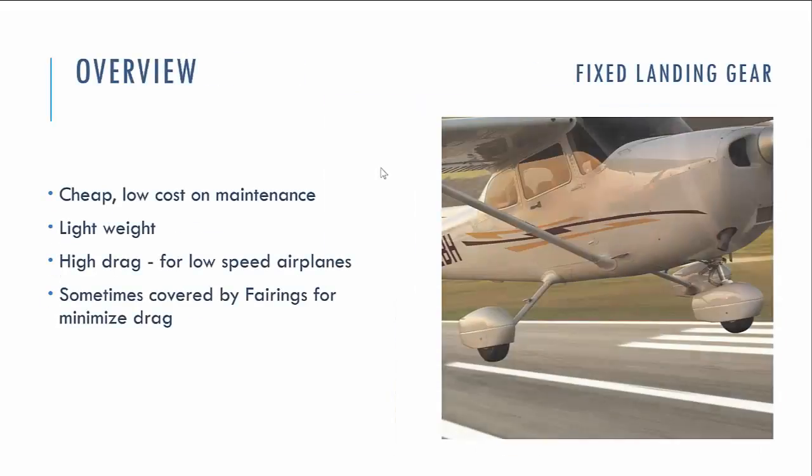So about the fixed and retractable landing gear, let's first talk about fixed landing gear. This construction is cheap and low in cost and maintenance because there are no additional elements in the construction, just springs, struts and wheels, nothing else. That's why this construction is lightweight.